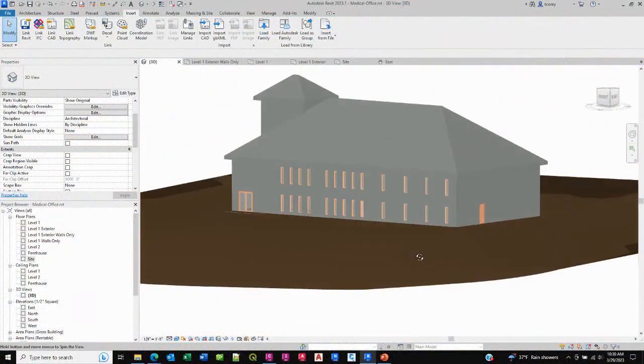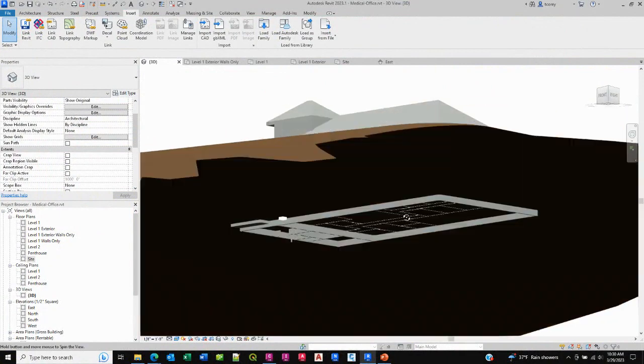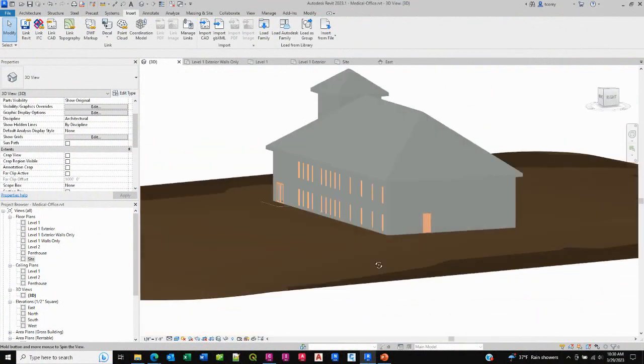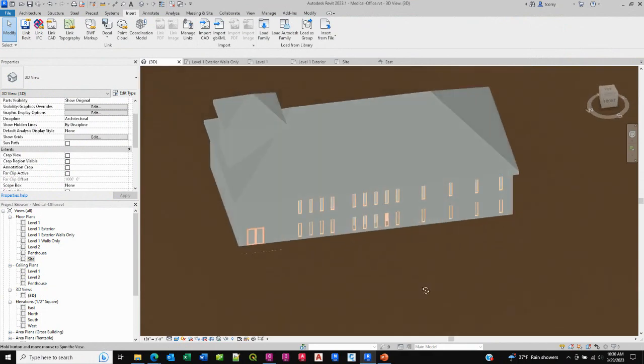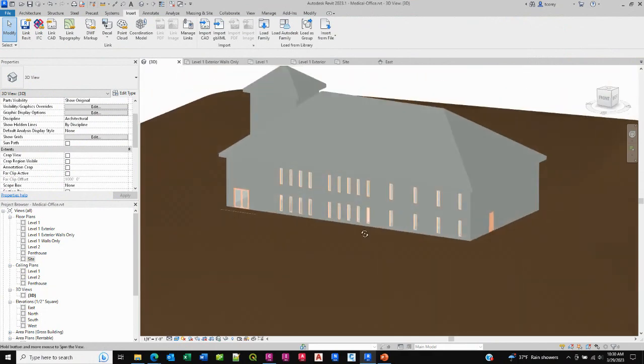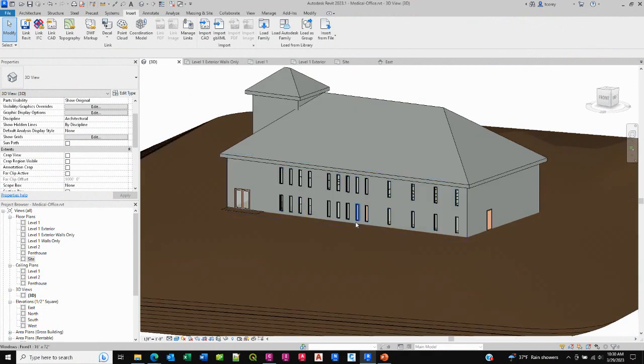The first one is, as a Civil 3D user, can I import a Revit RVT file directly into AutoCAD? No, from Revit, you have to export to a DWG. And then you can import the DWG, or insert would be the command. You can insert that into your Civil 3D drawing file.